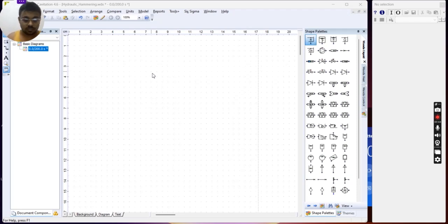If you visit any nuclear plant, in nuclear reactors there are coolant pipes which carry very hot liquid sodium. The temperature of the liquid sodium within the coolant pipe is very high. Again, it has radioactivity. As a result, the coolant pipe has to be made of very hard material. Again, due to radioactivity and other reasons like high temperature, it becomes very brittle. So there is always a chance of brittle failure of this material. That is a sudden catastrophic failure that has to be avoided.